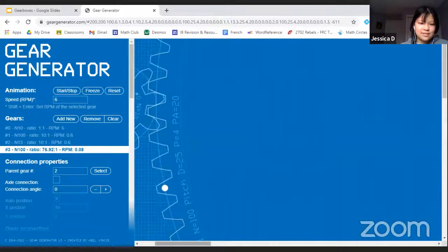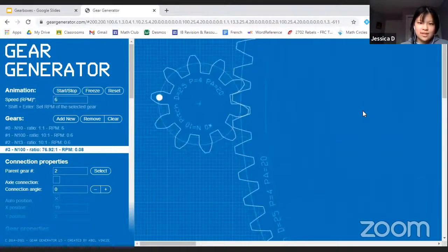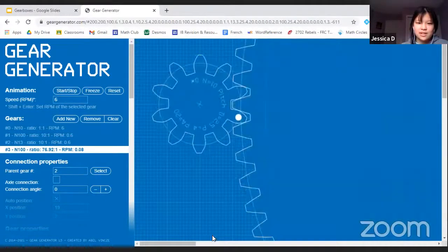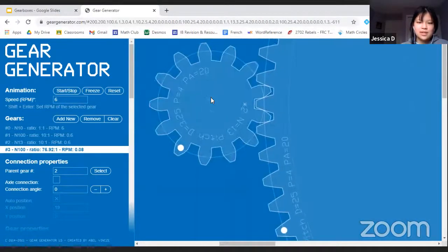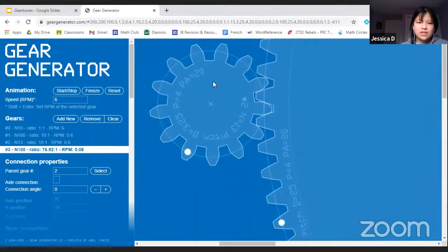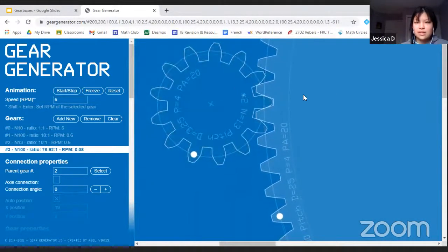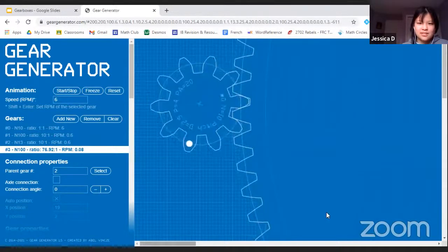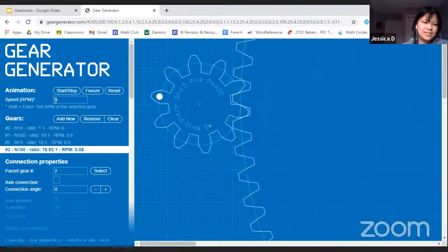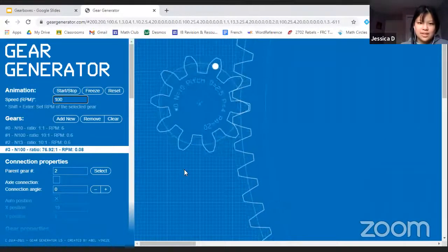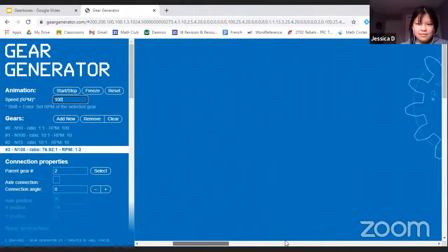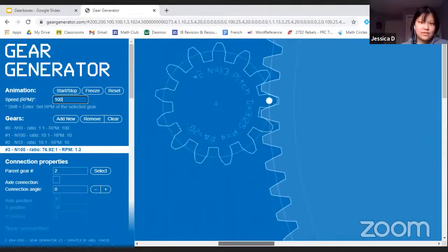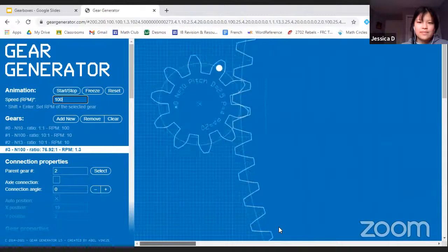so we have 10 teeth here, 100 teeth here. That's going to be a gear reduction of 10-to-1. This is turning at the same speed. And we're going to have a gear reduction of, again, 10-to-1 because 10 teeth, 100 teeth. So we start out with this speed. We end up with this very slow speed. If we increase the speed, maybe it'll help you visualize. So we're spinning that fast there. We're only spinning this fast here. So you can see that we've reduced the speed by 100-fold using this gear train.